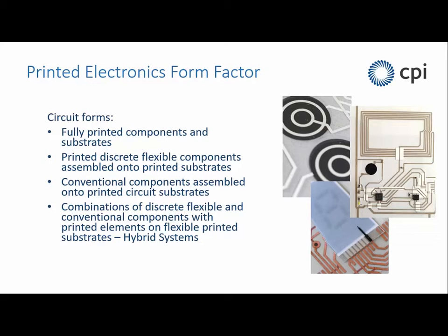Printable electronics, though, is a bit further away than that. We can print circuits by the kilometre, that's no problem. We can print sensor materials by very large areas of them. But the active components, we tend to make use of conventional, off-the-shelf components, so silicon, in fact, and other materials for all of the types of components we use on conventional PCBs. So what you tend to find with a printed electronic circuit is that it is not simply into a printer and produce a sheet of circuits.